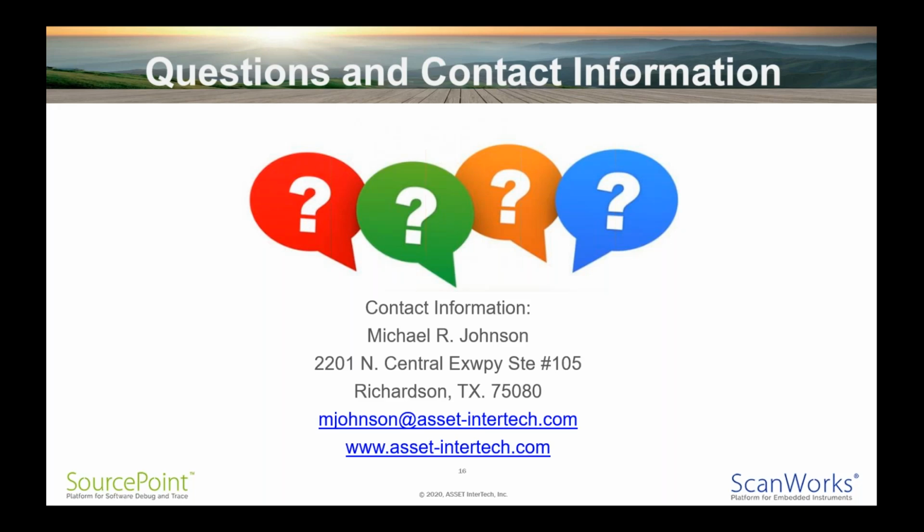Good question. Within ScanWorks, there's an import feature where you would import your BSDLs. Upon the first importing of those files, you would perform what's called a build, and that translates the BSDLs from just the text format into a binary format that can be used by the tool, by ScanWorks. So that's the first step.